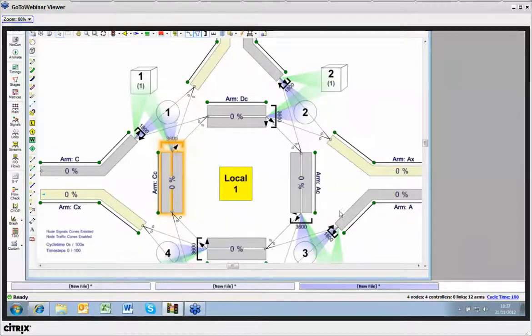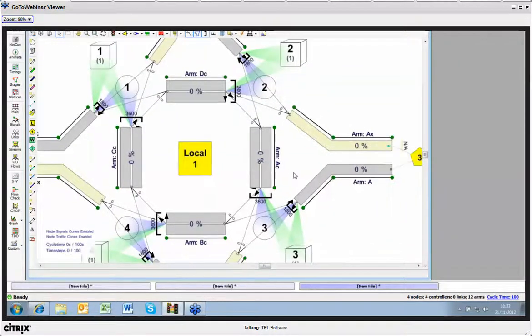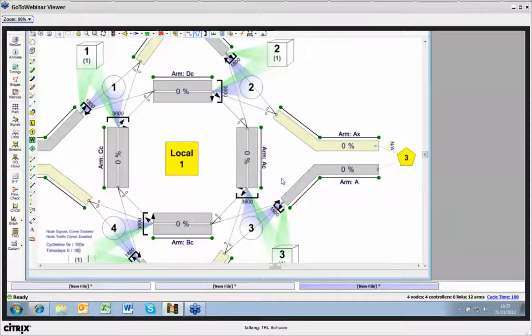The next thing I'll talk through is the optimization procedure. As we saw with the first junction I did, we had a very simple junction, and the optimization procedure was very, very quick. That's brilliant for that simple junction. That used the standard hill climb procedure that we've used in previous versions of Transyt. However, hill climb is a very good model for giving a very good answer in a very quick amount of time, because it's a very efficient way of finding the optimum result. What it doesn't guarantee is that it finds the absolute optimal result. So there may well be a better one out there.